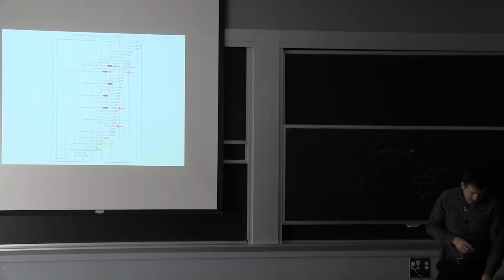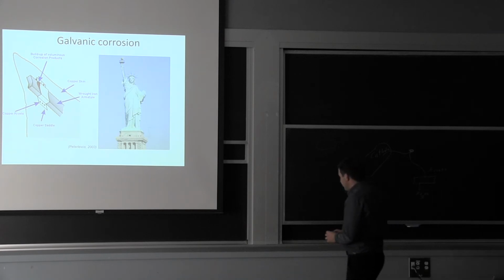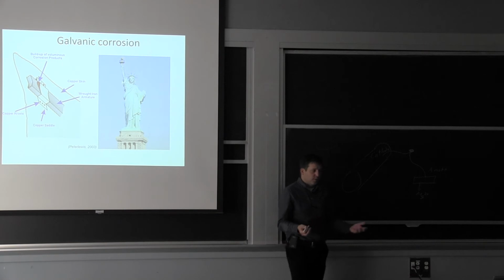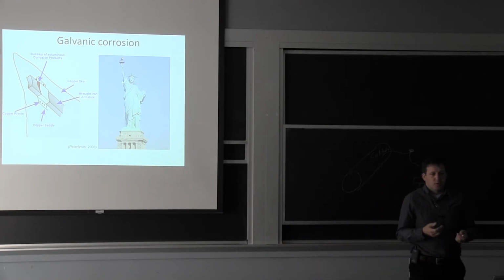All right, so the galvanic corrosion, there are ways around it. If you think about it generally, relative size is very important, and then of course the potential and what are the characteristics of the most reacting material. When it's aluminum, you're thinking, well, maybe I'll be okay because it's self-protected. If it's iron or steel, then that's where you get the highest risk of change.